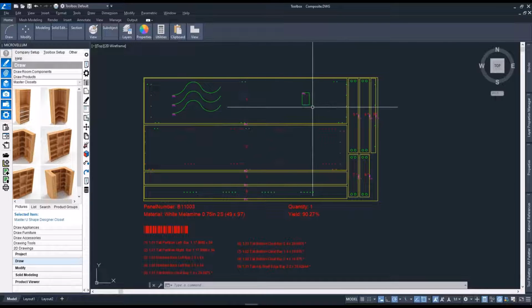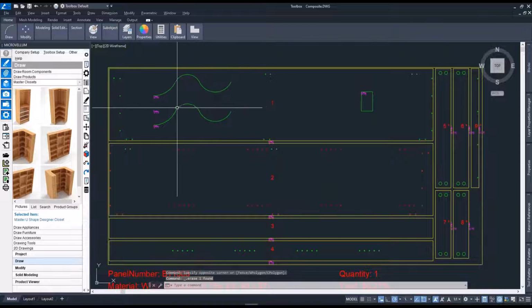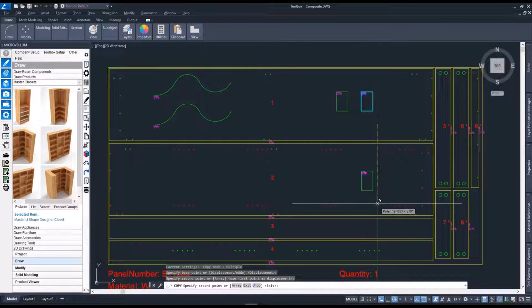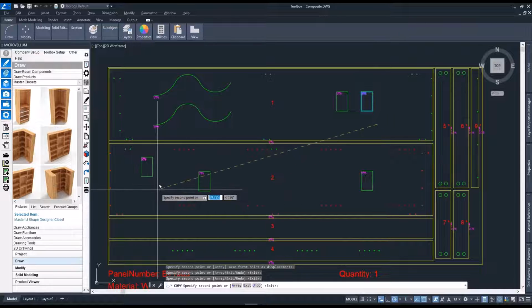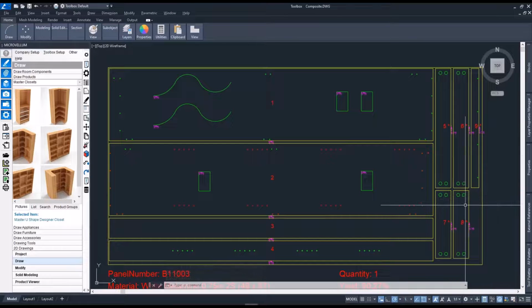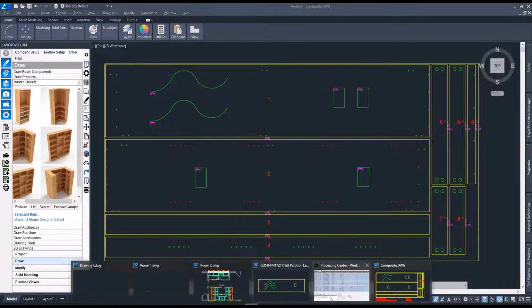Even at this stage, if you decided that you no longer need this center odd-shaped route, you can just simply delete that with AutoCAD. If you needed to have two of these outlet covers, or you needed to add it into individual other parts, you can do so here. You would make those changes graphically, moving around parts, deleting parts, adding parts to this process, and just telling Microvellum to update the G code based off of your drawing.